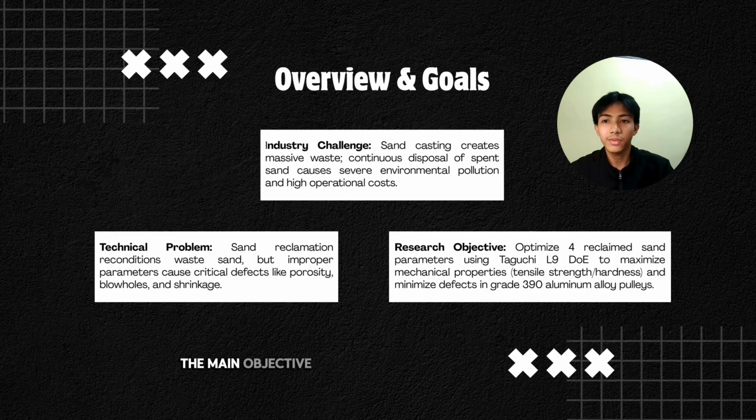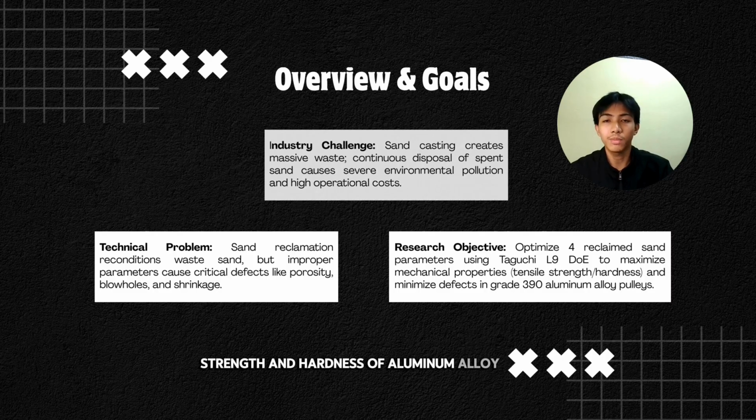Therefore, the main objective of this study was to apply Taguchi's design of experiments to optimize four key reclaimed sand parameters, namely sand strength, mold hardness, grain fineness, and moisture content, to minimize casting defects while improving the tensile strength and hardness of aluminum alloy pulleys.